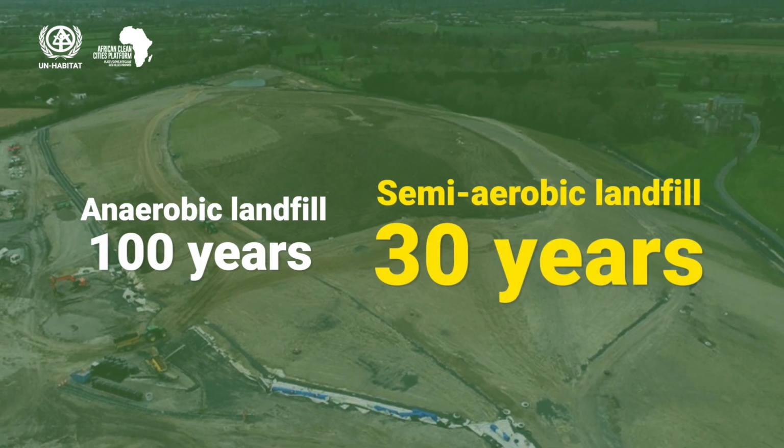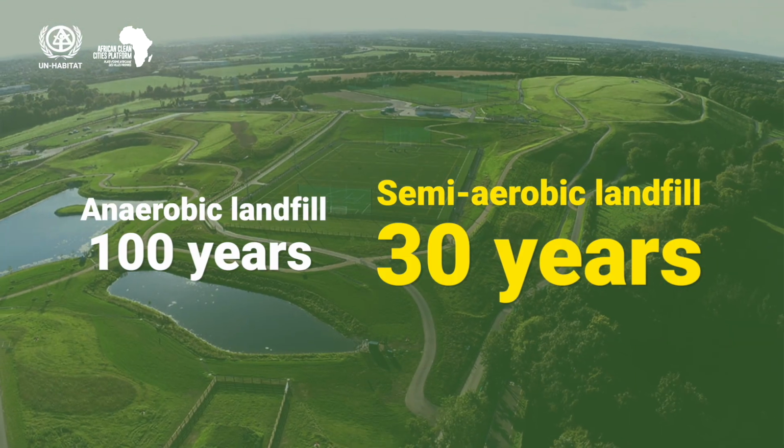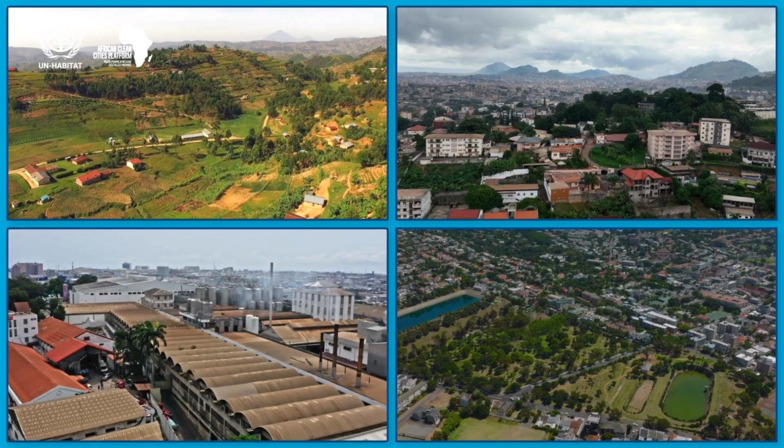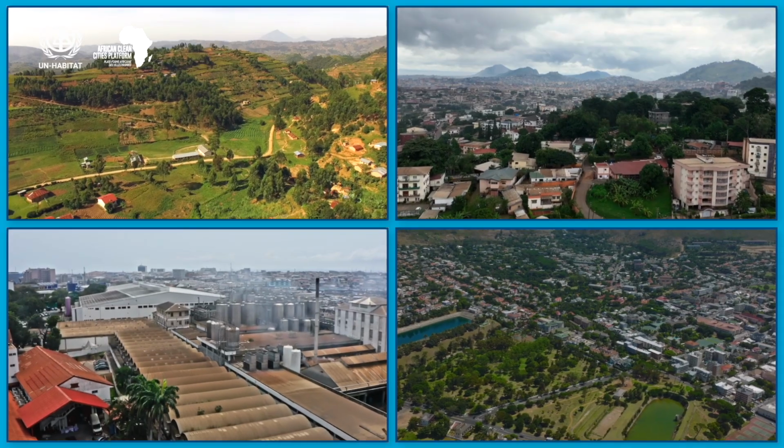Semi-aerobic controlled landfills offer a significant advantage in site stabilization, achieving stability in approximately 30 years after final usage and closure. This is a much shorter period compared to anaerobic landfill management. Once proper monitoring is conducted and site safety is confirmed, the stabilized landfill can be repurposed for various uses. These include green spaces, parks, and even low-story building developments, allowing the land to serve the community in new and valuable ways.